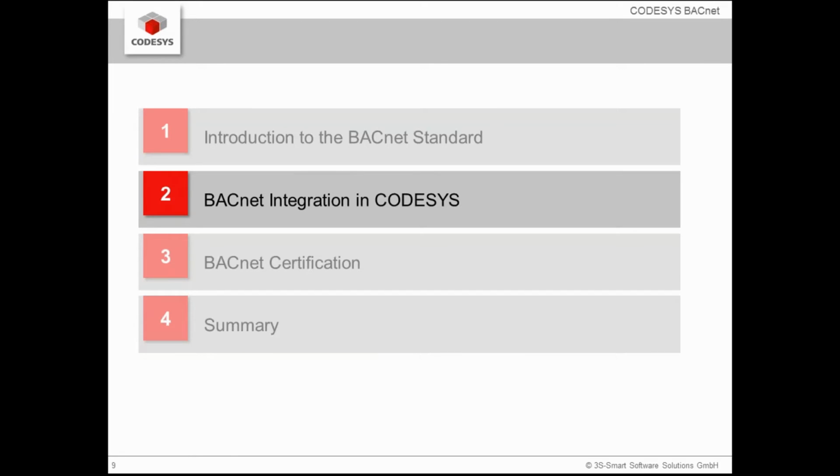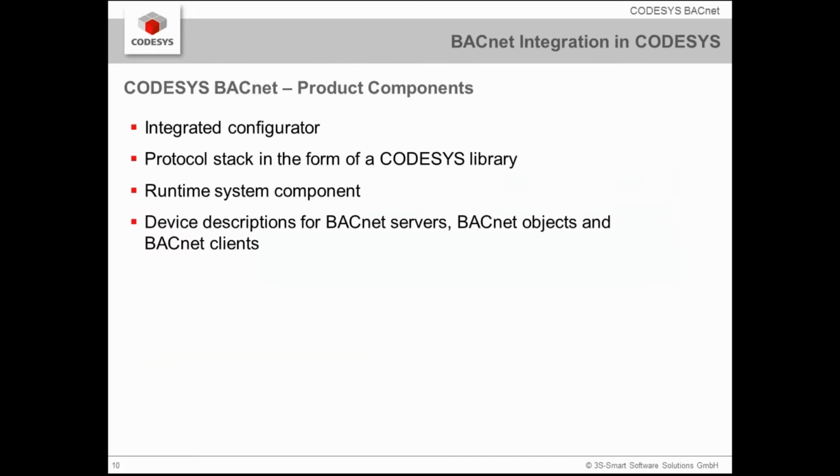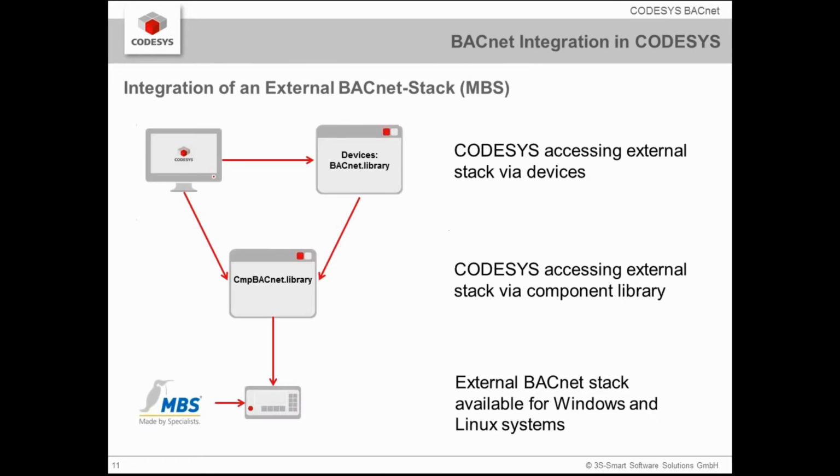So let's look to the BACnet integration in CODESYS. What are the basic product components we offer with CODESYS BACnet? We offer an integrated device configurator, a protocol stack in form of a CODESYS library, a runtime system component, and of course device descriptions for BACnet servers, BACnet objects, and BACnet clients.